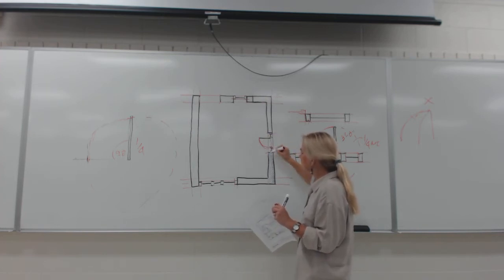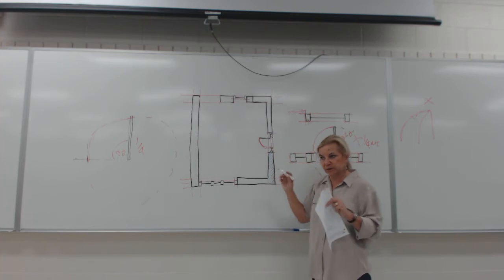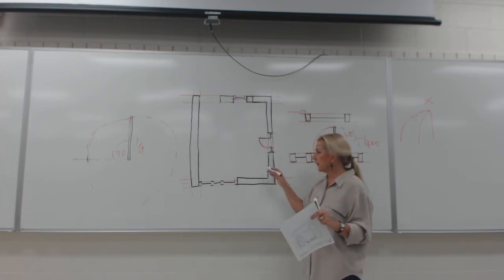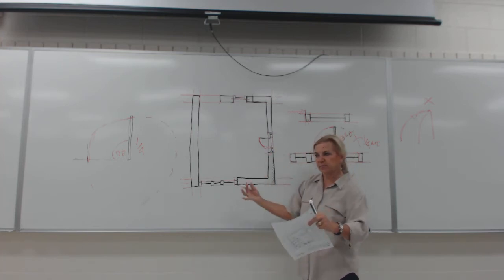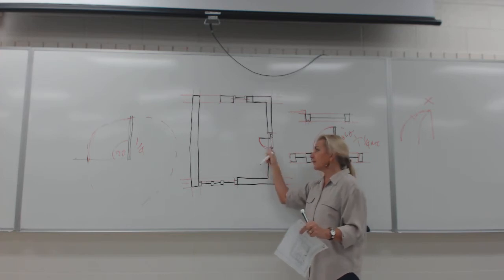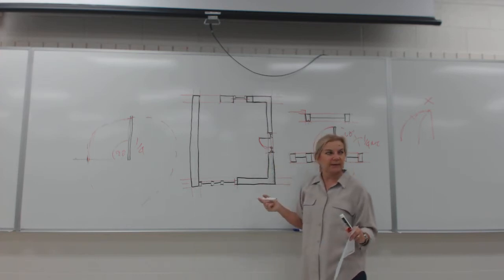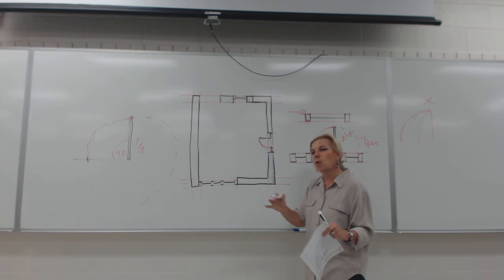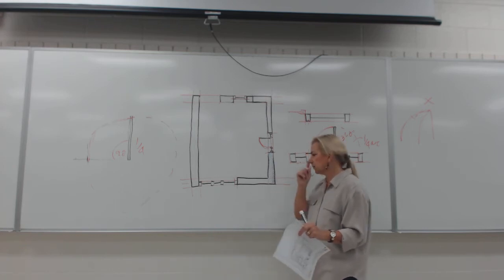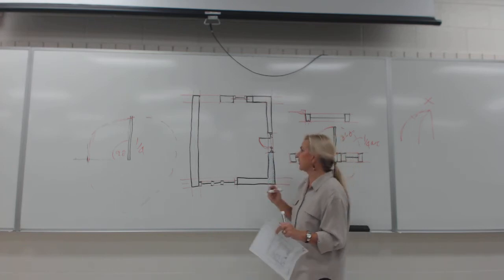Make sure you show these 2 lines because there is a threshold for this whole frame. We don't ever have exterior and interior meeting. We don't build our tile floor to the exterior deck, right? There's always a metal threshold, so the water and snow don't go in. It's tiny. You sometimes don't see it, but it's there.